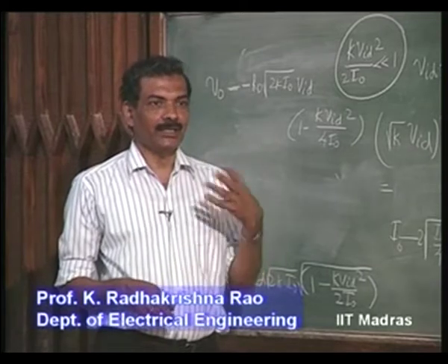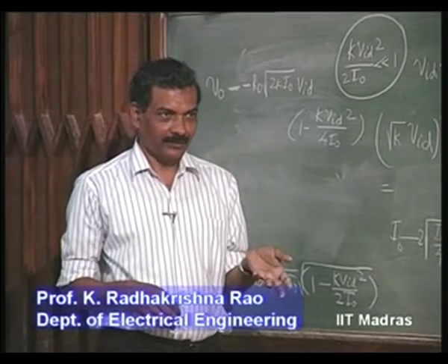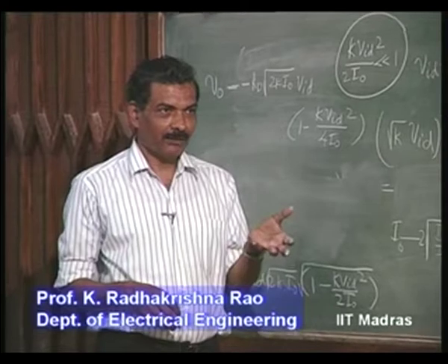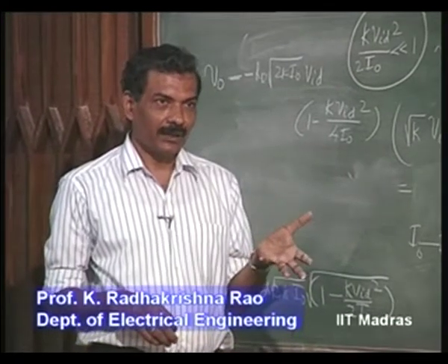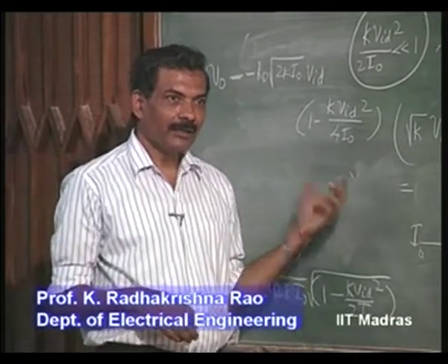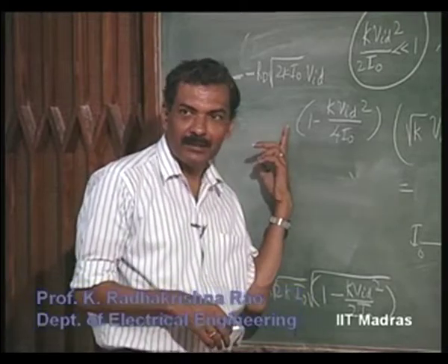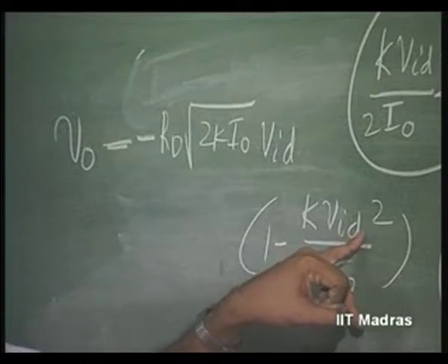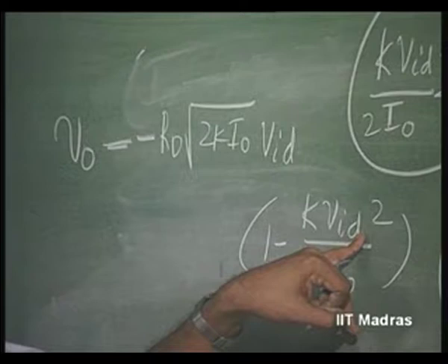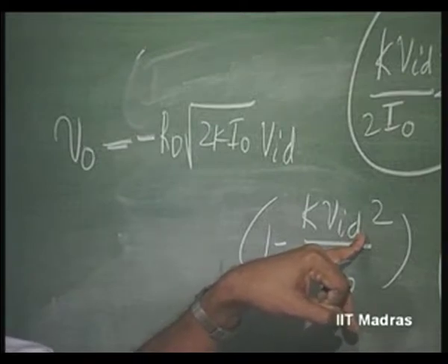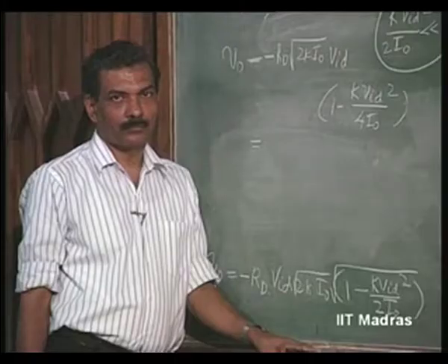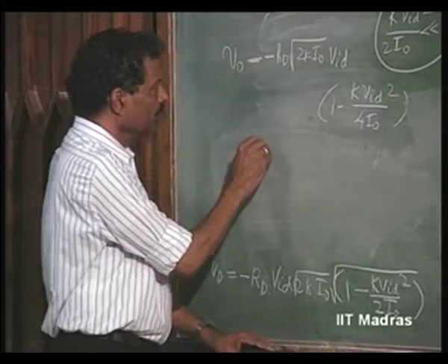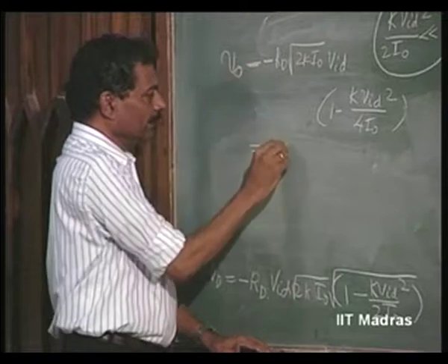The second harmonic is the first component, in fact, the only component that comes into picture for distortion, but it is going to be dominant. Here in the differential amplifier, you see that the harmonic component is what? Third harmonic, like in the case of bipolar junction transistor.